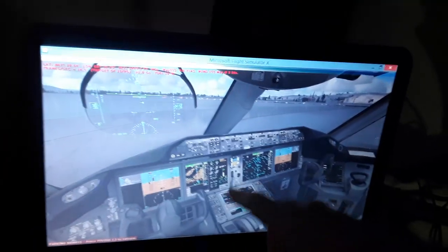Before flight, actually, we're going to input all the data of the aircraft for this flight. So we're going to create a flight plan, or a flight path, or a route. It's going to be displayed, as I told you, in purple. Also, it's going to be followed by the autopilot flight director system panel when we connect the autopilot. So also in the navigation display, you can see the magnetic North Pole, the geographic North Pole, and the magnetic variation depending on where we are in the world.